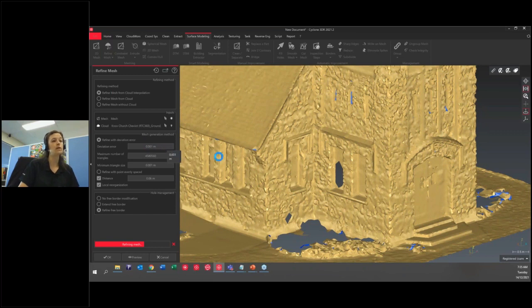And so that's how you do it. If you want more detail in here, you decrease the value and you'll get smaller and smaller triangles. There will be a limit, obviously, because it will depend on how many points you've got in the point cloud and the quality of the point cloud anyway. But here you could enter values like 0.1 mil or things like that. You will see that it will make thinner triangles and more details in there.